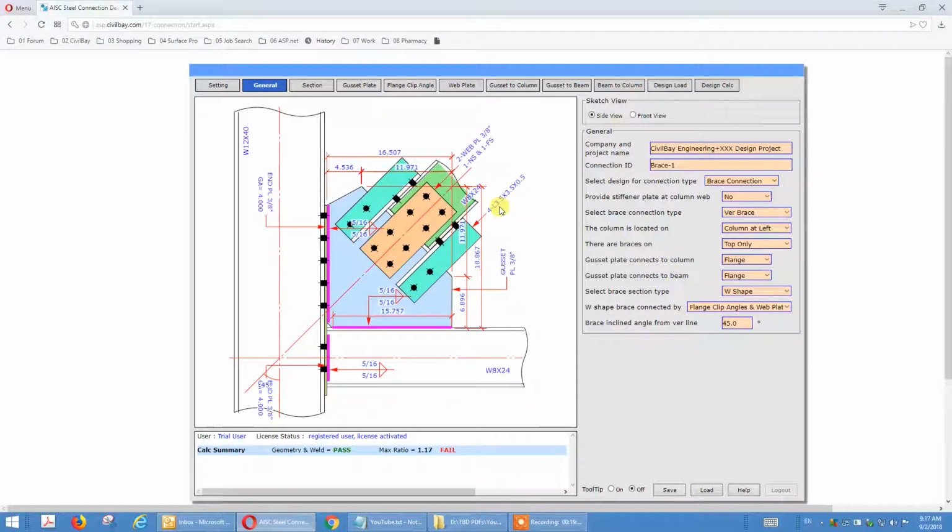Now that's W type of brace sections. That's W shape. That's the heaviest W shape brace. Okay, the brace load pretty much is close to 100% of the W shape tensile capacity, or at least more than 50%, like 65, 75% of the W shape wide flange tensile capacity, heavy brace.